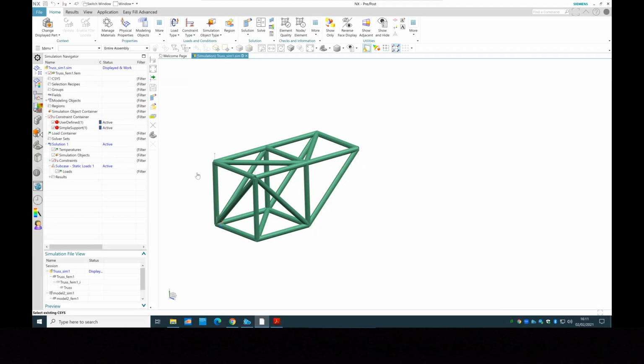So what we've done so far, we've done the constraint. Again, the first stage was mesh. We apply the constraint. We technically are making these scenarios for you. So as I said, we have the fixture, technically like hanging it from the wall, and then we have the support from the wall. That's why we use the simply supported. And in here we can see that actually we have done the constraint.